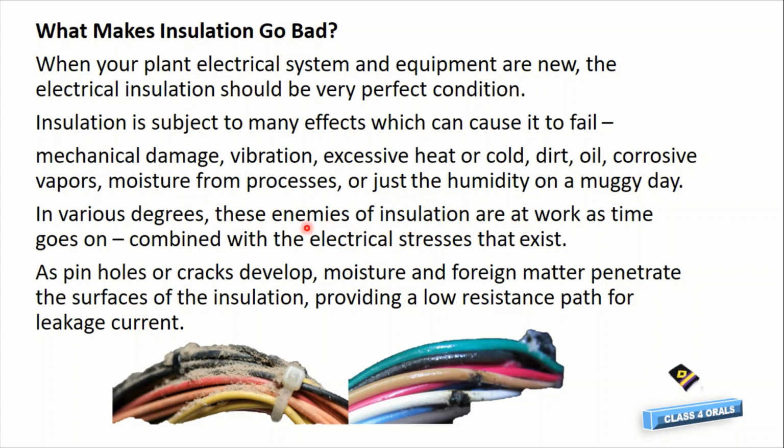So at this time there will be electrical stresses over the cabling. So there can be pinholes, there can be crack provocation, there can be cracks of the winding and the insulation. So what will happen? The current will say, okay, I am finding a very good low resistance path for my flowing. I will follow this leakage path. That is why there will be less current flow and it will leak over from here. Thereby insulation resistance will be bad.